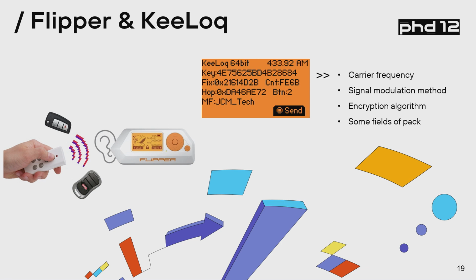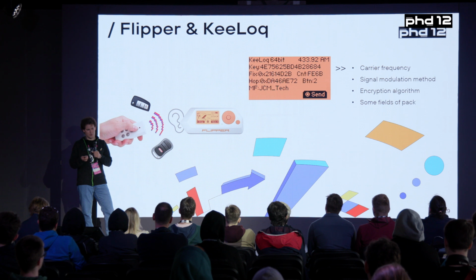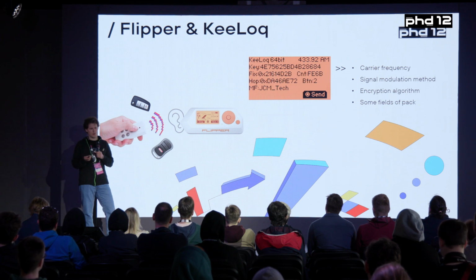I was initially thinking of using Flipper because when I started my study, Flipper was all the rage. So I decided, how about I sniff the radio frequencies with Flipper, and it provided some interesting results. Because with Flipper, for example, you can identify the carrier frequency of, say, a simple remote control, because Flipper can do some simplistic spectrum analysis for you.